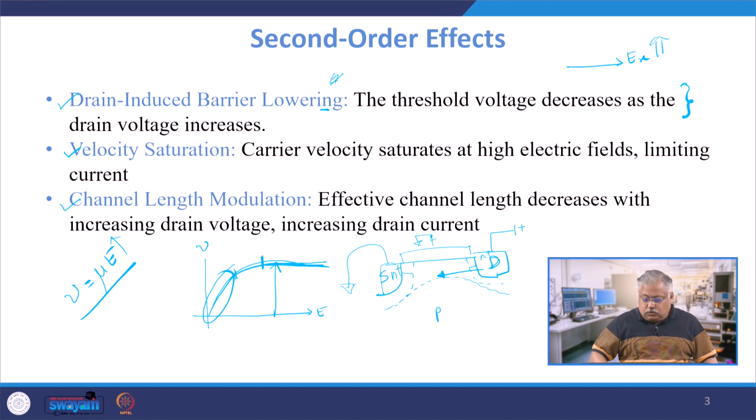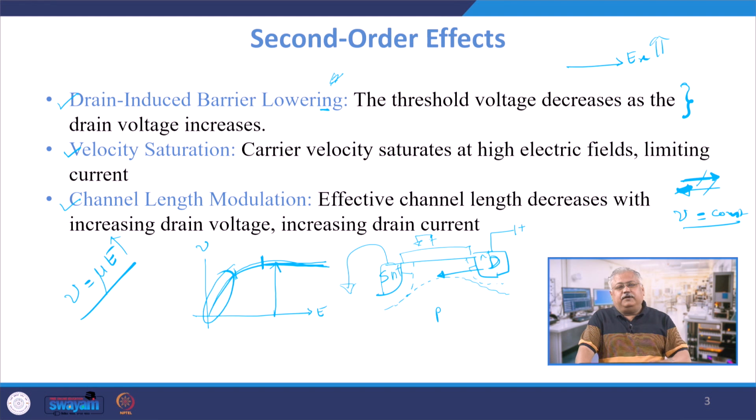So we have one force along this direction, and another force because of scattering in the other direction. When these forces become equal, the velocity is constant, acceleration equals 0, and the effective force on the particle is 0. That is known as velocity saturation, very prevalent in all short channel devices.